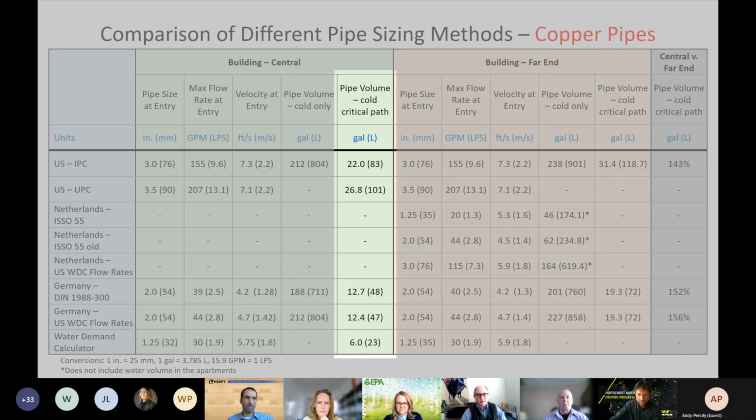If you have a storage water heater, even a small one is 30, 40 gallons. Most are 50 today in the US for apartments or dwellings with this many fixtures in them. And that's way more than the volume of the plumbing in the apartments. And so the hot side has much more residence time than the cold side does, doesn't it? Absolutely.